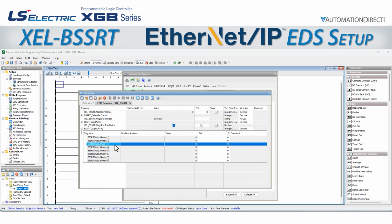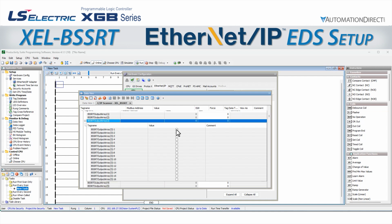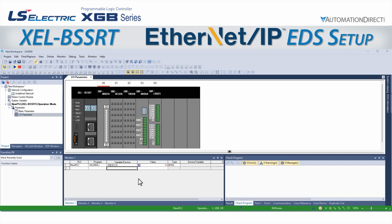Productivity also has a cool feature to allow us to look at the individual bits within a word. We right-click on the element and select Show Bit of Word Details. It breaks out each bit as true or false. We can write a value of 1 to the word, which will correspond to the first bit being on. We send the edit to the PLC, and if we look back at XG5000, we see that sure enough, the output point has changed to on.